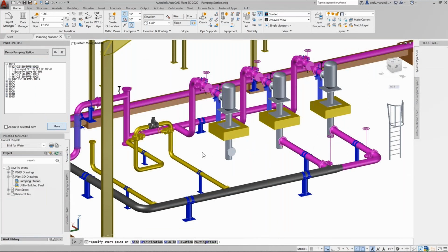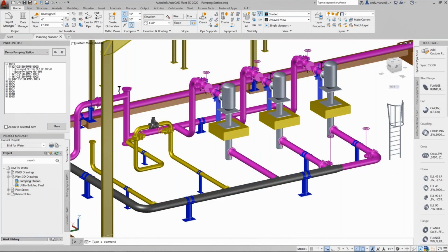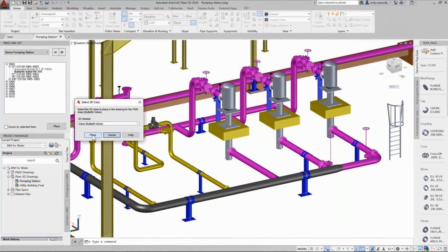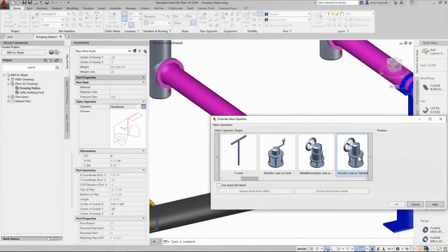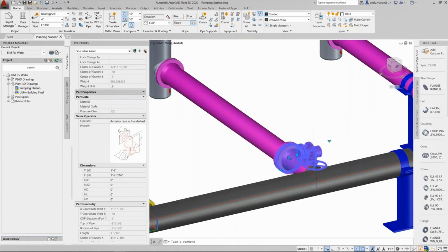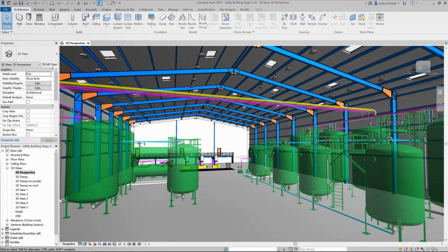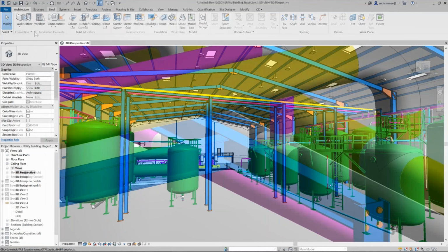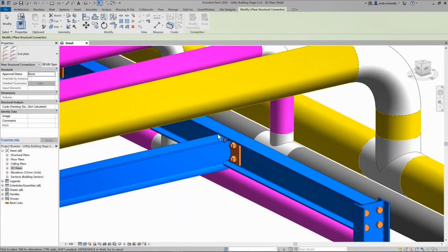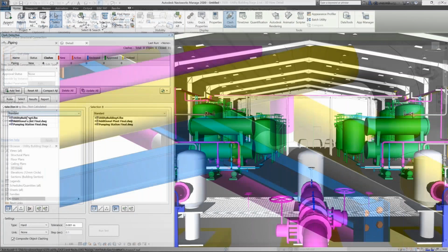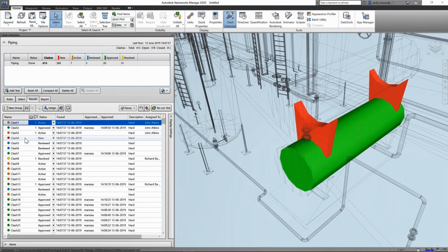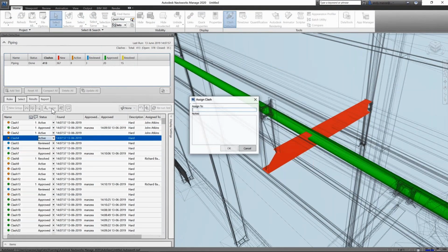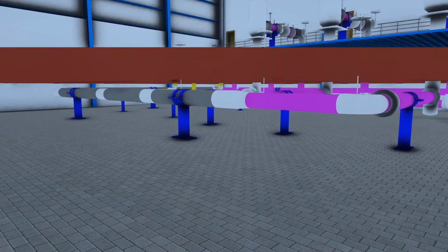The piping model is a 3D representation of the P&ID, and the data can be accessed while we are creating the piping. The modeling tools in Plant 3D allow teams of designers to quickly lay out equipment, route pipes, and ensure proper connectivity. Once the equipment has been modeled, we can combine the Plant 3D model with a Revit building to create the piping support steelwork with the aid of fully automated steelwork connections. Utilizing a federated Navisworks model, the project team can collaborate to detect and manage clashes between the pipework and supporting steelwork, as well as the remaining structure and services.